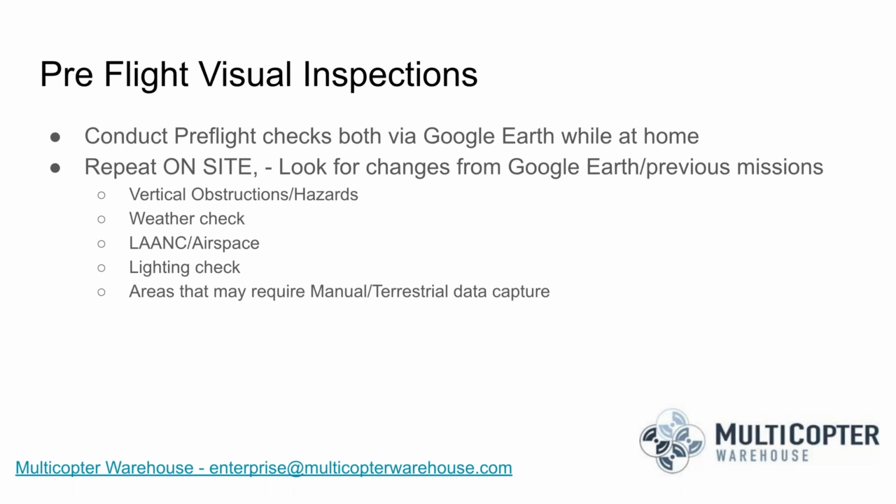Right. Now, a decent aircraft that we just got in is the Autel EVO 2 Dual, because the thermal on that is 640 by 512. That doesn't solve the complete agricultural vegetation analysis issue. It just gives you bigger images that can be processed through something like Pix4D. And the sensor on that camera is a radiometrically accurate sensor, so yeah, you can do mapping with it.